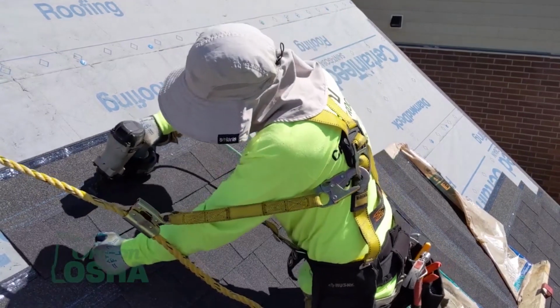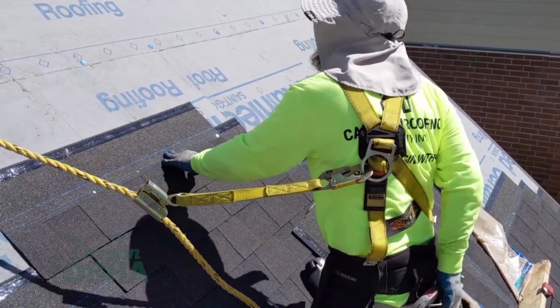When it comes to working on the roof with the different materials, whether it's asphalt shingles or metal or tile or slate, there are different aspects for each one that you have to be careful of. Asphalt shingles, when it gets hot, really hold the heat, which can enable dehydration and heat exhaustion to happen. You can burn your fingers a little bit. The granules are pretty rough, and if you lay enough shingles, you can actually wear through your skin. In wintertime when they're cold, they're stiff and rigid. If the wind starts blowing, I have been on roofs where the wind will actually grab the shingles and start popping them on you.